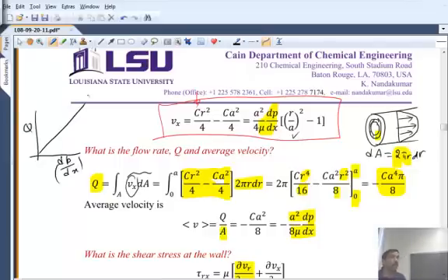Okay, the question is, over what range of Q will I get that to be a straight line? This is the question that we asked earlier. Will this relationship hold for any flow rate? The answer is no. When the Reynolds number becomes greater than 2100, this relationship goes quadratically. It goes much faster. No, it should be the other way. You should correct me. That is, to pump an additional amount of fluid, you need a much larger pressure drop. Okay, so the relationship is quadratic, but it is going this way.